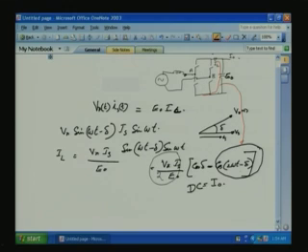That will generate a ripple voltage across this one, and let us see what that is. If this is cos 2 omega t, we will integrate. Approximately, let us take the ripple peak as IL hat. If you integrate, it is divided by 2 omega C. For the capacitor, the voltage delta V is equal to the integral of 1 by C I dt.